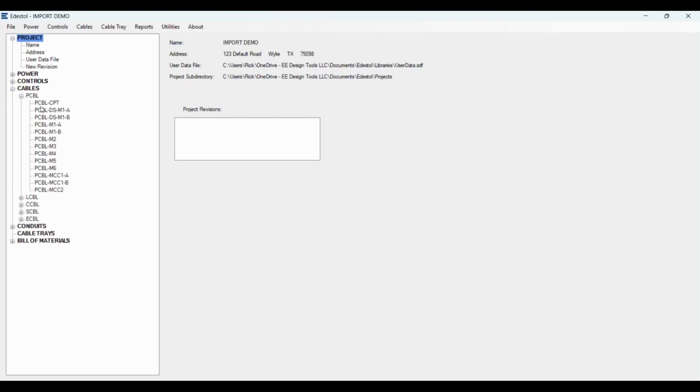You have P cables for your 480 volt, basically 241 up to 1000 volts. You've got L cables, which is your 120, 240 stuff. Then you've got control cables, each associated with a control device, and signal cables, which are your shielded cables. Then you've got your communication cables; in this case they're all UTP, unshielded twisted pair Ethernet, but they can be fiber or coax, whatever.